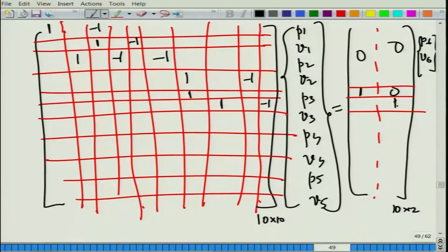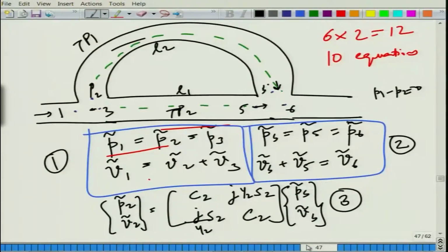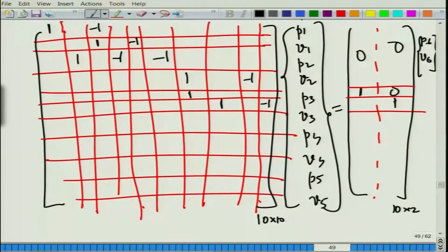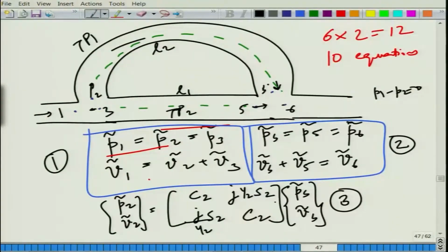Now comes the crucial point of putting the transfer matrix in the proper form. So, what I am going to do is simply put this thing where these things are. So, this is the 7th equation. So, it's the 7th row. For simplicity, or for your better understanding, I can number the rows. Now, P7 is where your P2 is, that is the row. So, P2 minus C2 times P4.